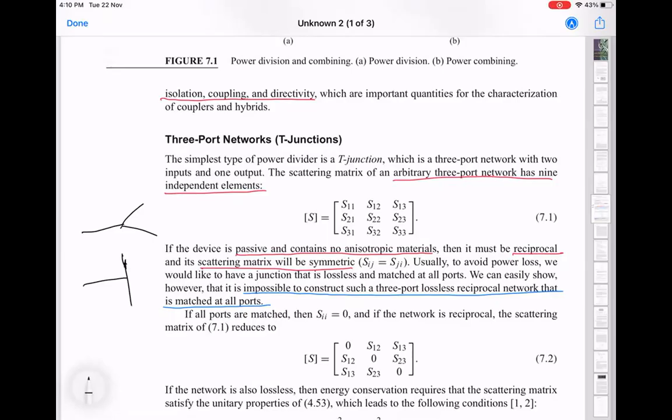So these are not the transmission lines we have been discussing. These are now waveguides where you can again have wave propagation by using solid rectangular tubes and things like that. Those are often used at very high frequencies, usually above 10-20 gigahertz, but you can use them even at the usual frequencies of 1 to 10 gigahertz as well. But they tend to be very bulky because, again, the sizes of those things are related to the wavelength. So the smaller the frequency, the larger the wavelength. So we will not look at waveguide stuff much at all, except for in passing.